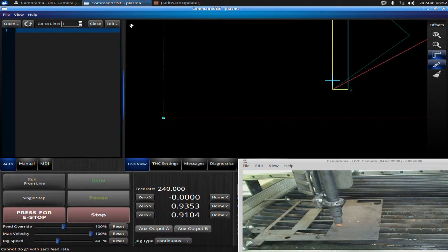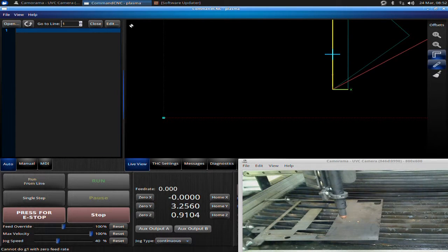The most common is your gantry itself physically runs into something, and that is usually going to be something on the rails, as far as a welding BB or some debris from grinding, especially if you grind next to the machine. You want to wipe your rails down when you're done with them. Before you fire the machine up, I recommend taking a brush and just brushing off the rails.